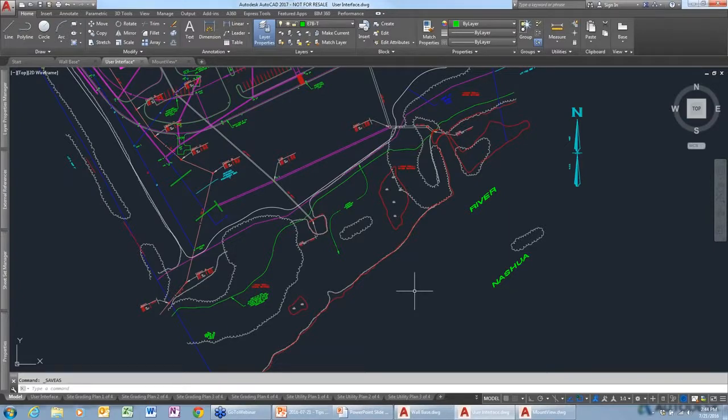So let's see, Nauman, if we have a couple of quick questions, and then we'll finish the last slides. Yeah. There was a comment about alias edit. You don't have to close AutoCAD. You can just use the oldie-but-goldie command called reinit, R-E-I-N-I-T. Thanks, Tim, for pointing that out.